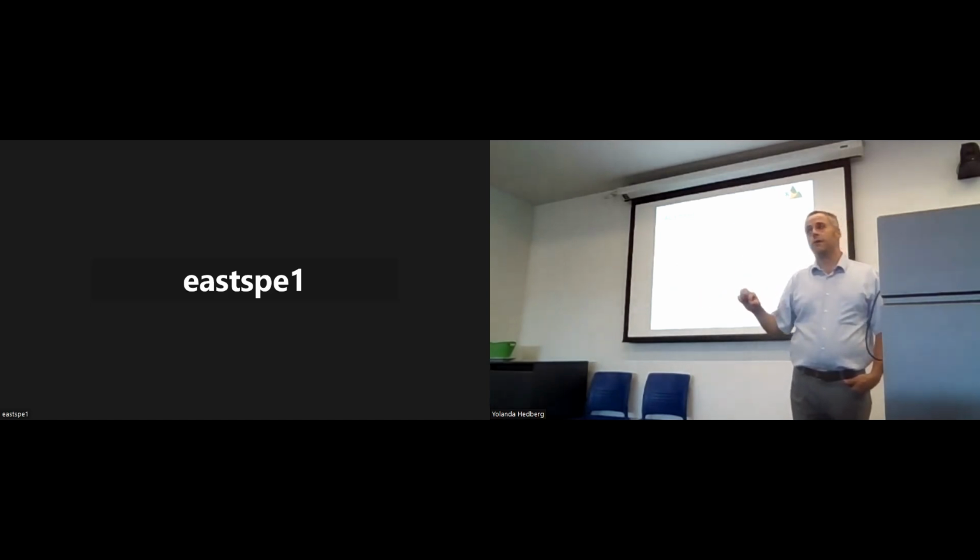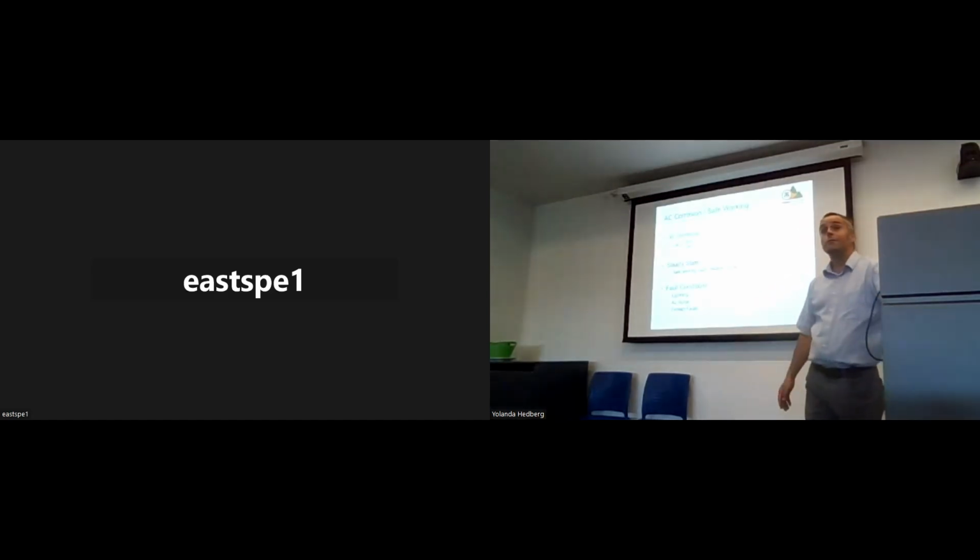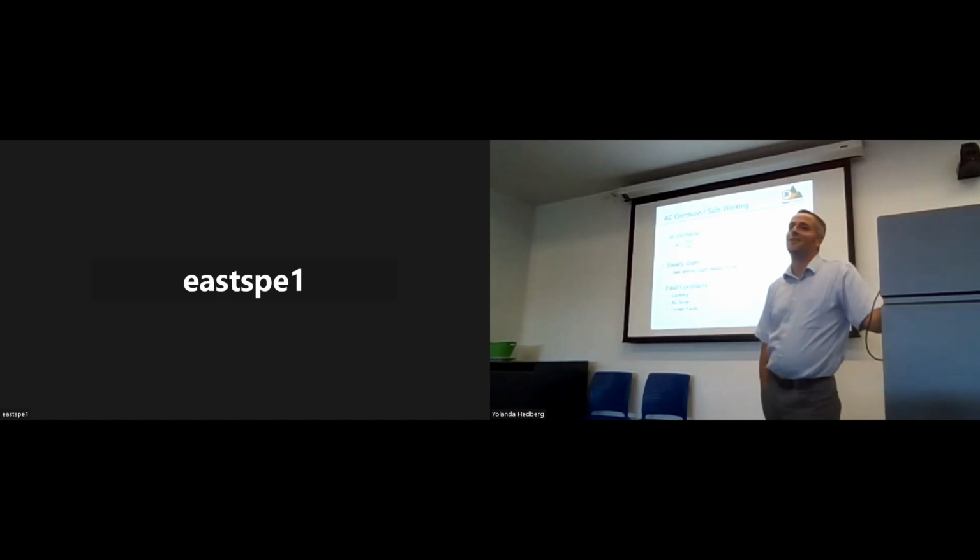The second scenario is fault conditions. If there is, what happened to our tall metallic structure? Lightning. If lightning strikes the power line, what happens to the lightning? Most big power lines have shield cables that capture the lightning. Where does it go? To the ground. It goes into the ground using copper. And where is that ground? Oh, is this a meter away from my pipeline? Oh, really? That has to be modeled.